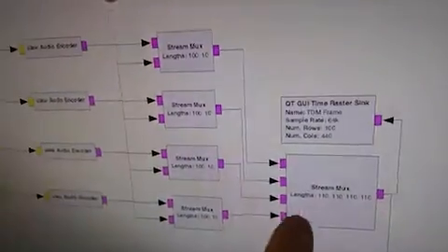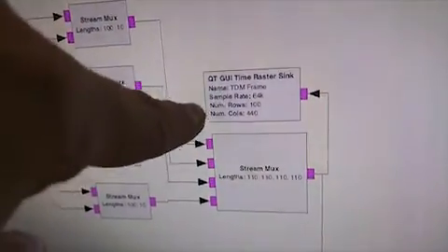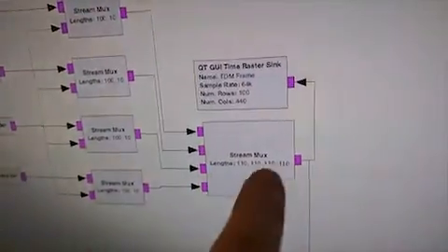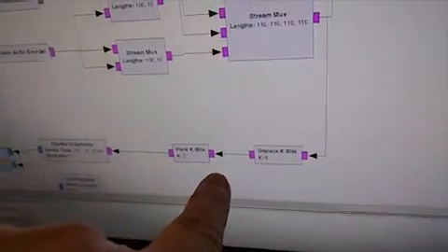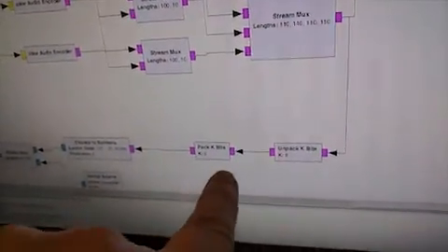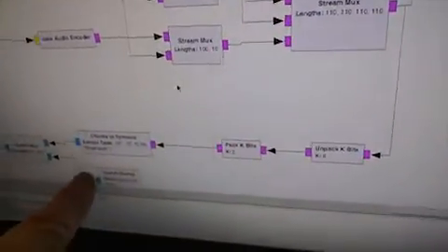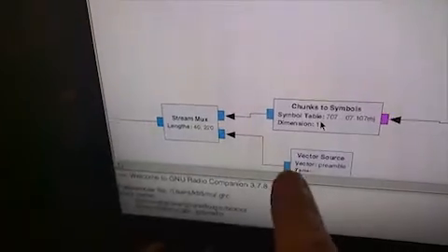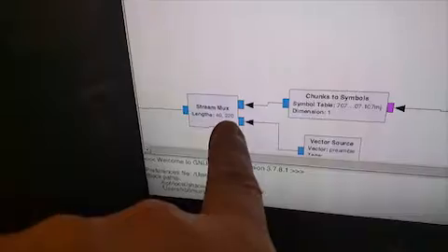And then all 4 of these streams go into this multiplexer together, and it gets peeked at by this time raster sync, which is just another on-screen visualizer. The multiplexed stream comes in here, gets unpacked, and packed again. I'm not sure what that's all about, but it's something relevant to how the data format works. Maybe they'll tell us. Then it gets turned into symbols and multiplexed with the fixed preamble by this multiplexer here. And now we get to scroll again.